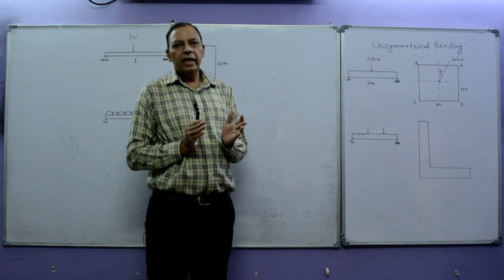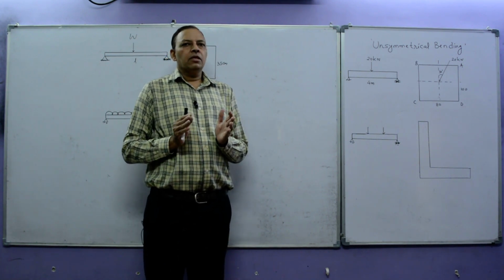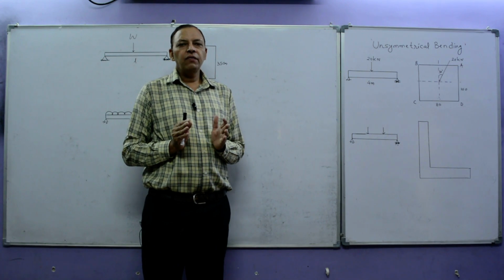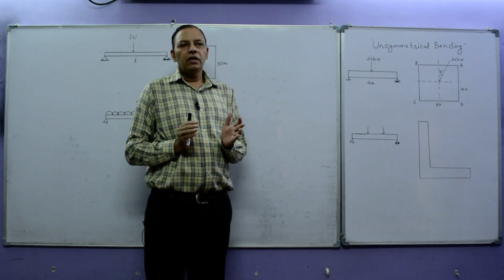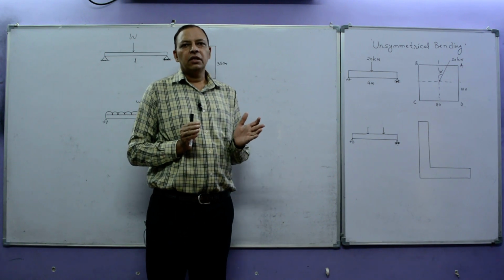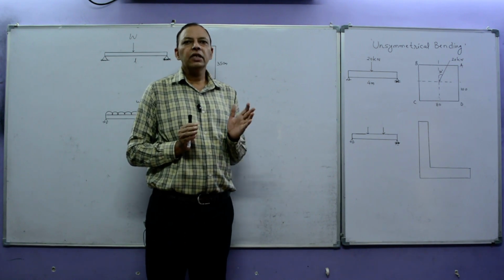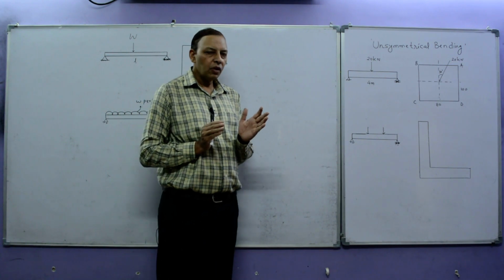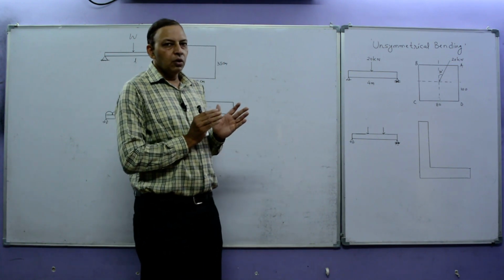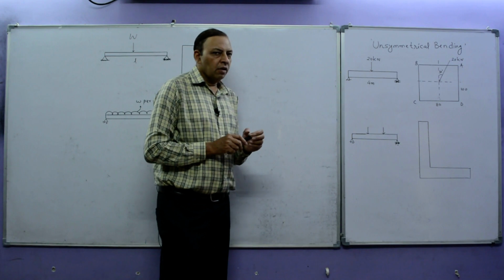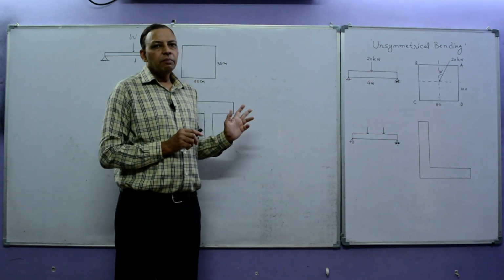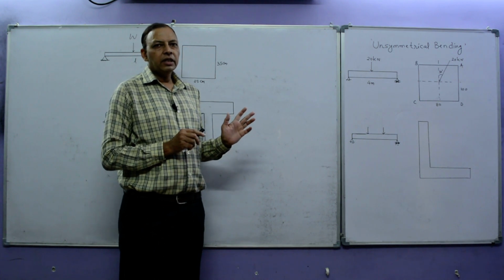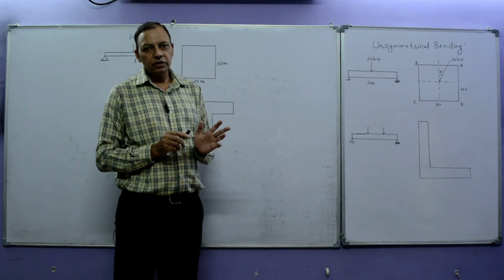We find that rectangle, circle, square have 2 axes of symmetry, and a semicircle will have a single axis of symmetry. So the 2 things are: bending moments do not act in a plane of symmetry of the member, and the cross-section area is not symmetrical.